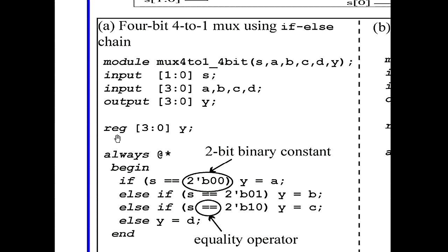Well, it turns out in Verilog, whenever you use a signal within an always block, you must declare it as a reg type. Sounds a bit odd, but it's for historical reasons. I would prefer if they just called it a wire and worked out where it resides, but you'll get an error if you call it a wire.